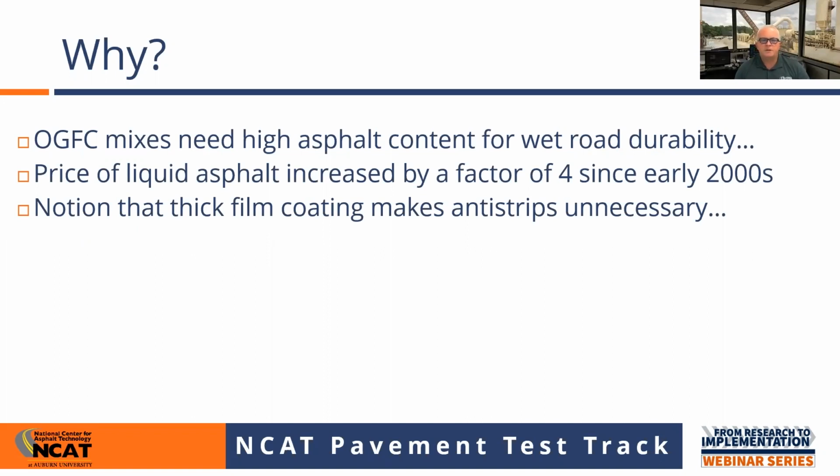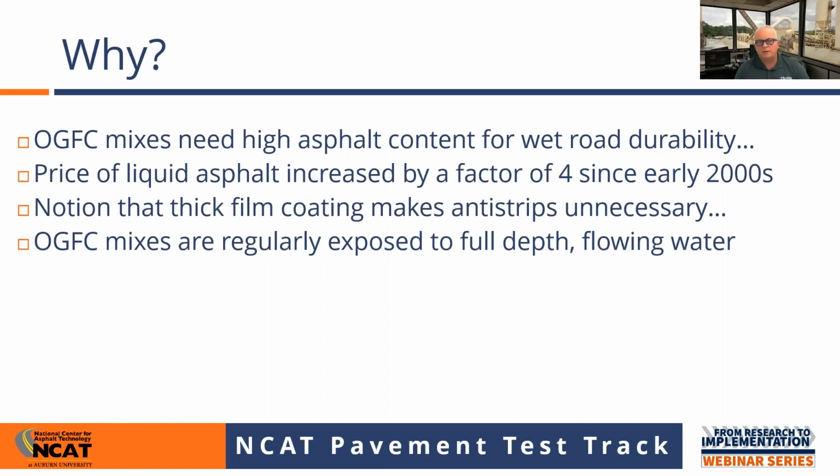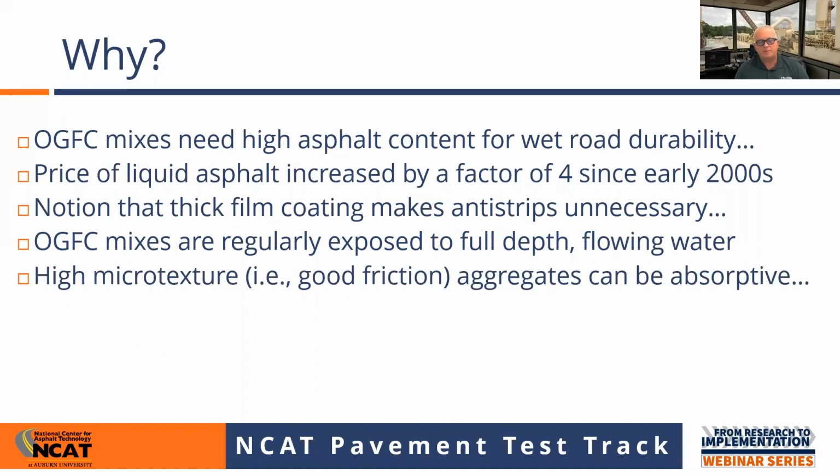Some agencies have the notion that we don't need anti-strips for these mixes because they have thick film coatings, but these mixes are regularly exposed to full depth flowing water. So if you ever had a need for an anti-strip, it's this type of mix, either hydrated lime or liquid anti-strip.